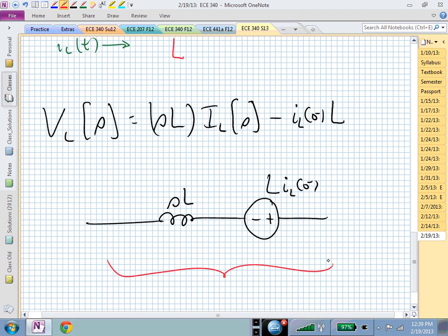This entire piece is the total voltage of that inductor, V sub L, and you could do a KVL around this and see that this voltage drop is equal to the right-hand side if we remember that our inductor current is flowing from left to right. Again, we're obeying this passive sign convention. The inductor current is coming into the positive terminal of that inductor's voltage.